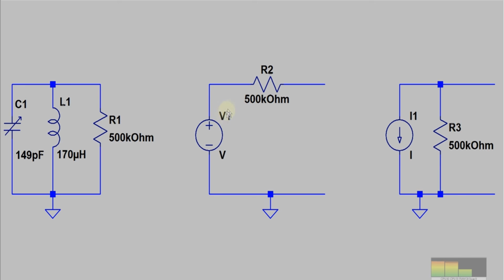As you can see, with a very high Q factor AM reception coil, we also get a very high output impedance, and we have to take care of that, especially when it comes to crystal radios, because many things are done wrong in crystal radios.